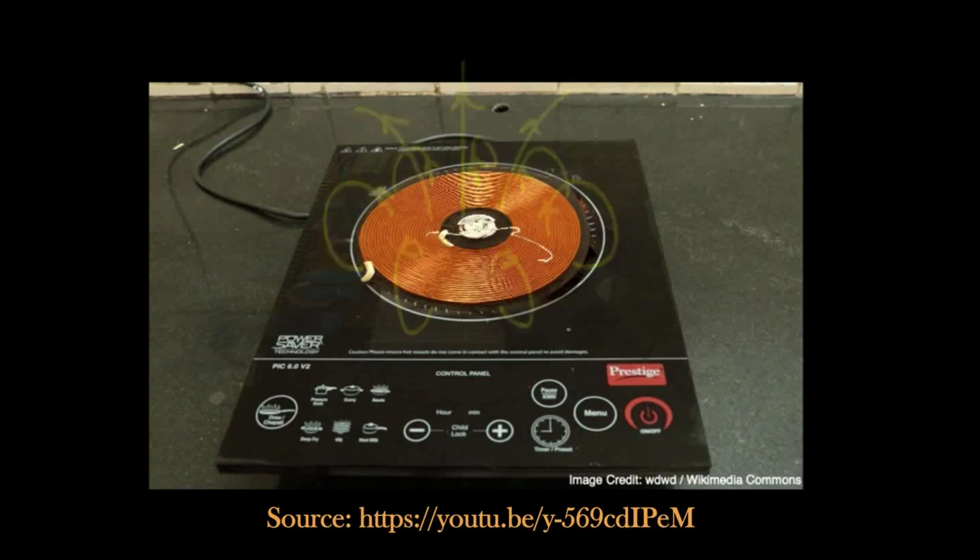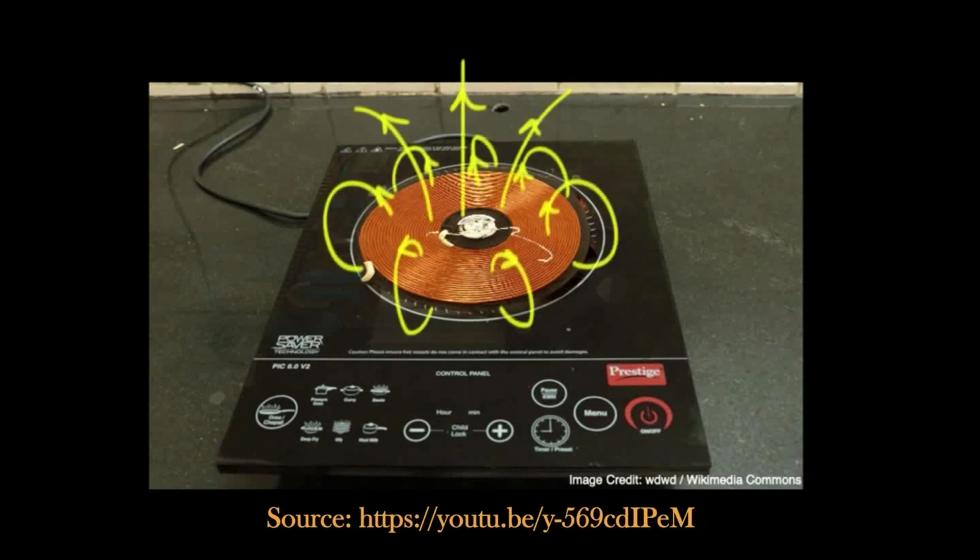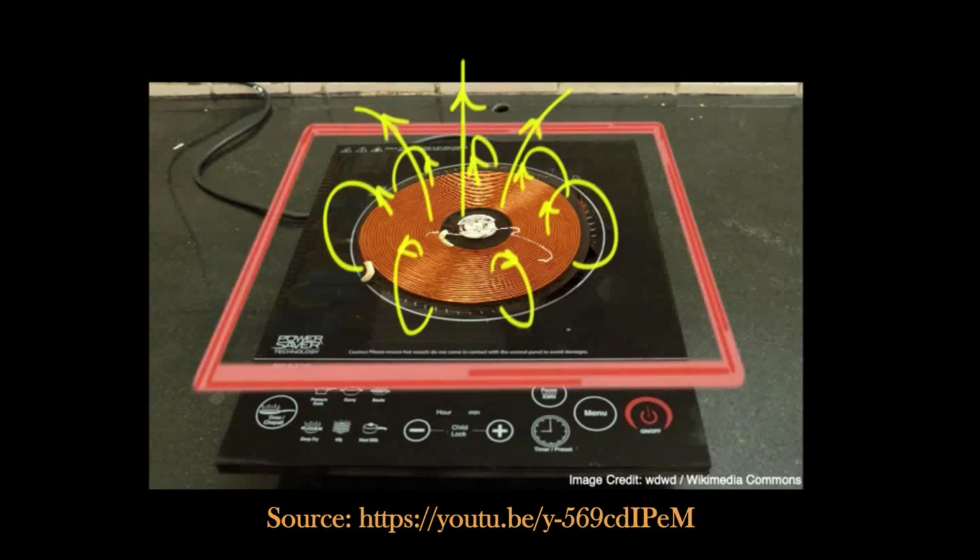So imagine this is how the magnetic field is generated. It's continuously fluctuating. And that's all that our induction cooker does. It does not produce any heat. All it does is produce a fluctuating magnetic field. But how does that boil our water? We'll get to that eventually. But for now, instead of thinking about keeping a vessel on top of this, let's keep a rectangular loop of wire. What would happen? Because the magnetic field is fluctuating, we have changing magnetic flux through the coil. And from Faraday's law, we know that that produces an EMF. And as a result, there will be an induced current in this coil.